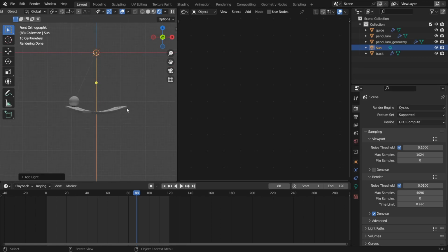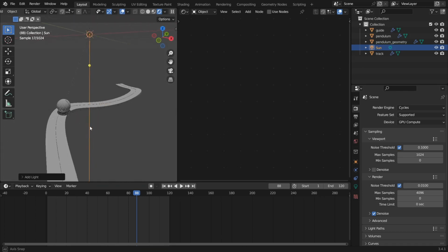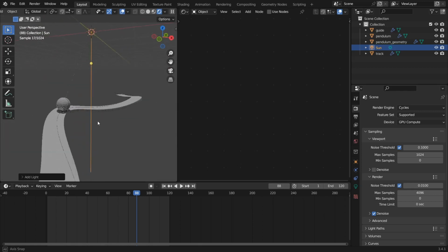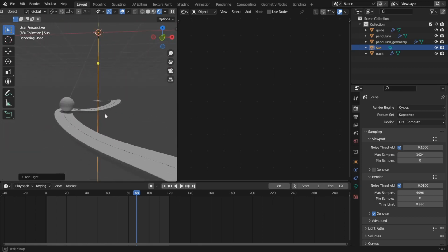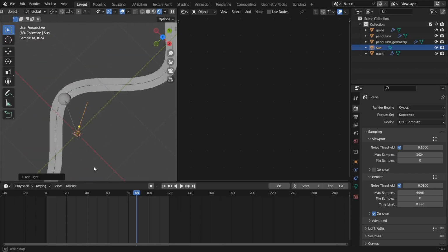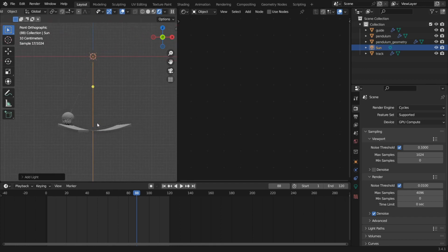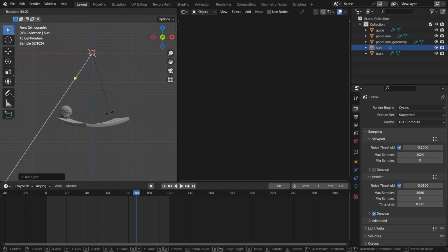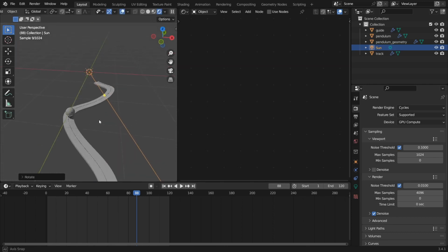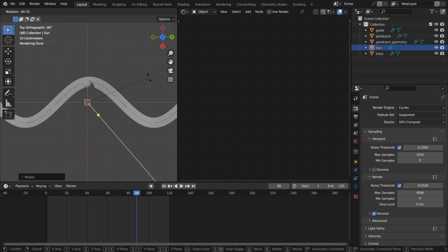By the way, if you want to snap into an orthographic view on any side, when you're navigating with the middle mouse button, so click down on that middle mouse button and drag to rotate. If you hold Alt, it'll sort of snap to one of these orthographic side, top, or bottom views. So in one of those views, or any other view, you can press R to rotate, and rotate the direction of that sun directional light. I'll just rotate it to the side there, and then I'll move to the top, and I'll rotate it a bit around the Z-axis as well.